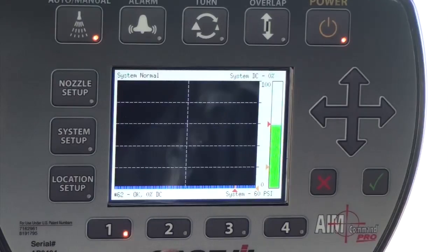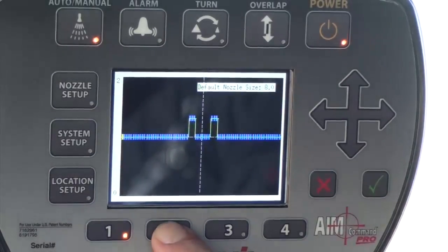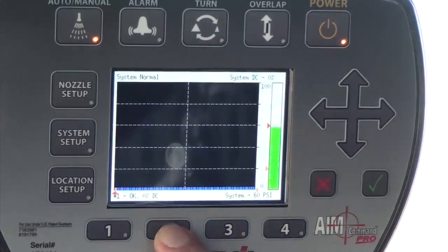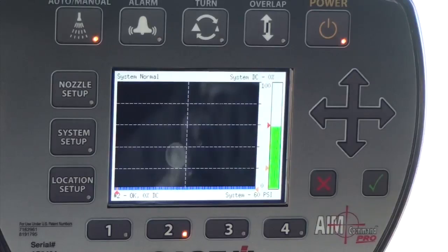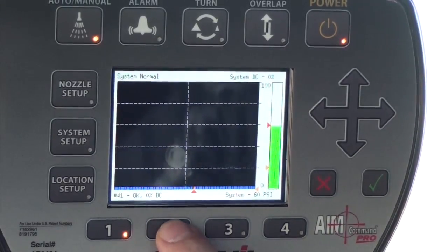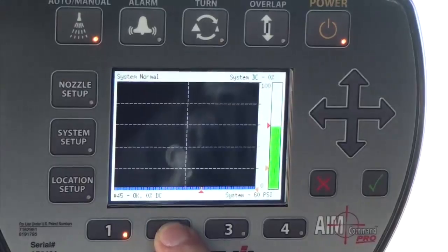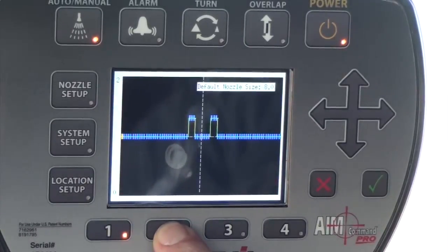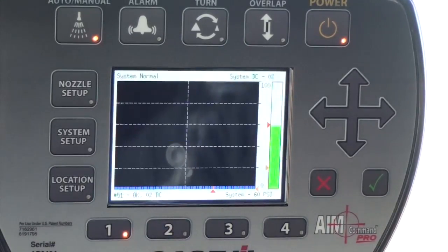The 4 boom presets are readily available at the bottom of the ProView display. To toggle between any of the 4, the operator needs to simply hold the desired button down until the LED on the chosen button illuminates. Also, notice that a brief touch of the button will actually show the configuration that is saved to that button, but will not select it.